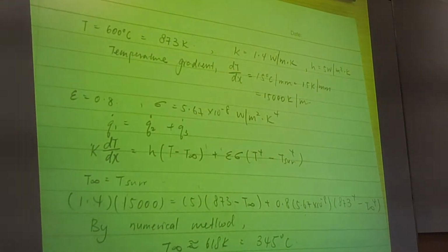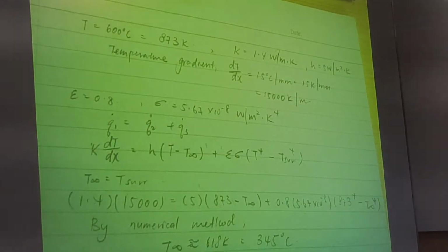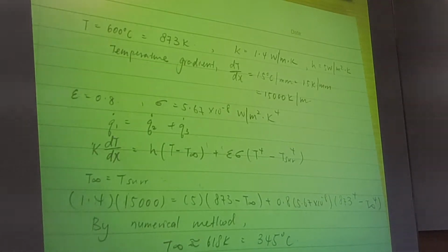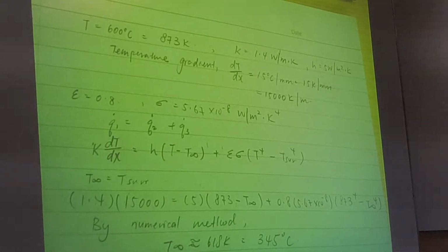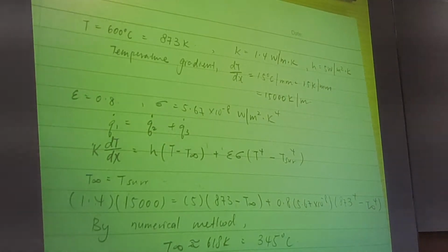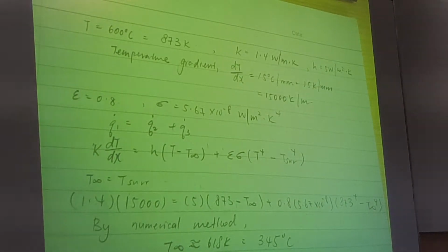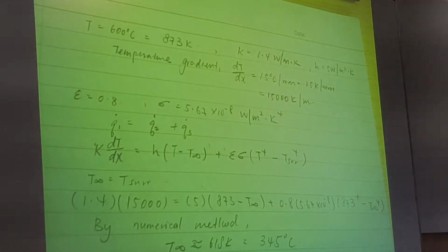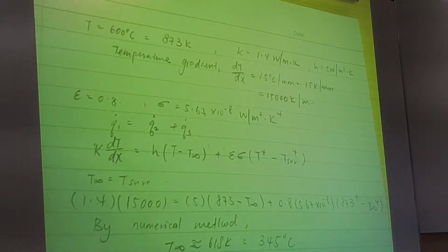Just one problem: when you apply the energy equation, we should use heat rate instead of heat flux. Using capital Q is better, with the surface area A involved. The other thing: when you write down Fourier's law, there is always a negative sign. What's the reason? Because dT/dx, the temperature gradient, is a negative value. Then combined it becomes positive. But you cannot neglect the negative sign, just to show you understand this. Very good.